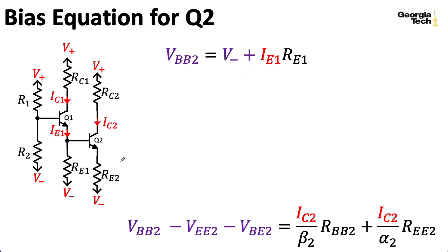All right, so what about the current source? Well, I would zero out this voltage source. And again, I'm cutting the line here. So the voltage that we see here would just result from this current flowing through RE1. So that's given by Ohm's law. And the thing that's a little different here than what we've seen before is I do see a plus here because this arrow indicates that we're pushing current into the node, which is going to raise the Thevenin equivalent voltage.